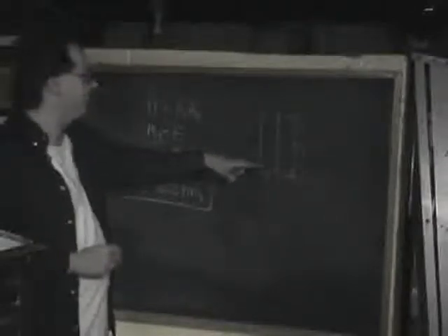So the pressure is going to be force over the area of the column. The total mass being the height times the area, that's the volume of the column, times the density of the water in the column. That's the mass. Multiply that by the acceleration due to gravity. Force is mass times acceleration. That gives us the force exerted at the bottom of the column by gravity pushing down all this water above it, and then divide that through by the area of the column, and we get the pressure.